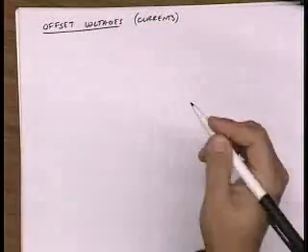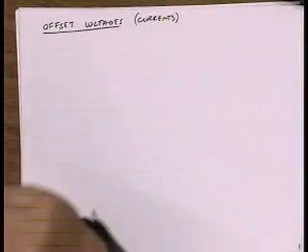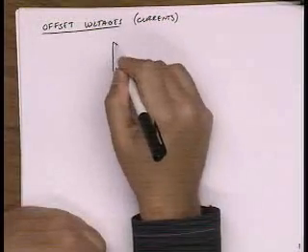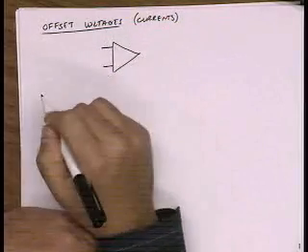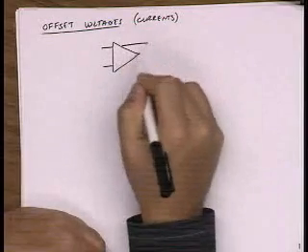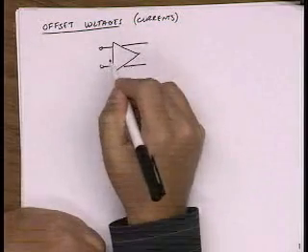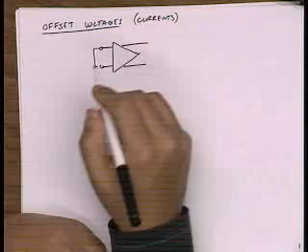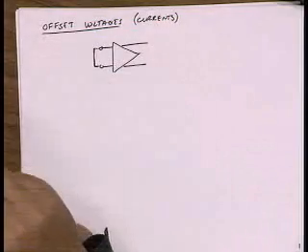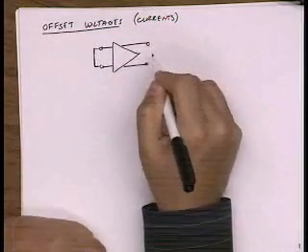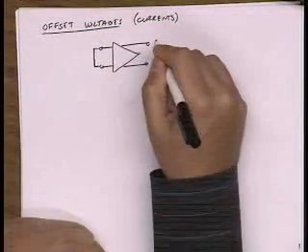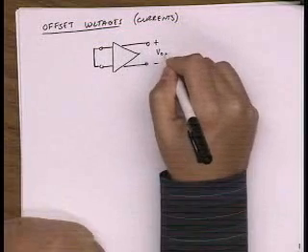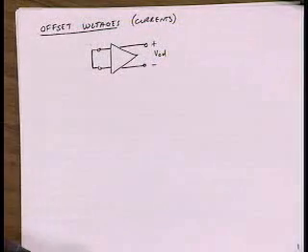The idea is that if you build an amplifier, say I build a differential amplifier like this, and let's say it's fully differential, and let me ground the input. So I apply 0 differential input voltage, and therefore I would expect to see 0 differential output voltage, but instead I observe some V output differential. And so what's going on?